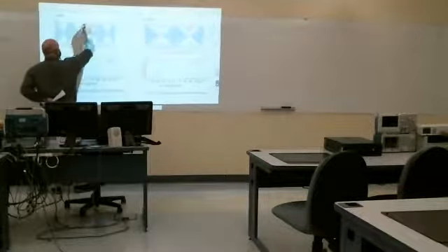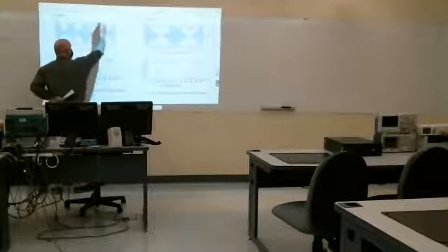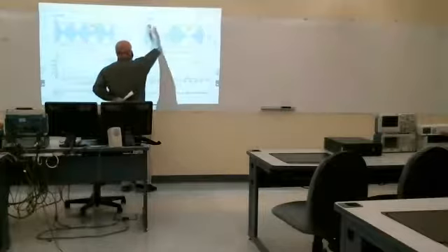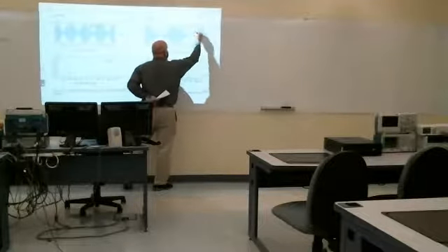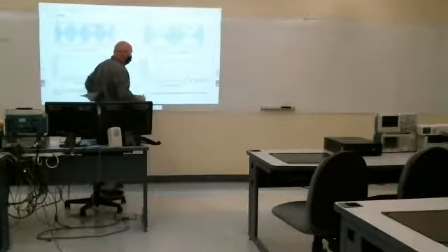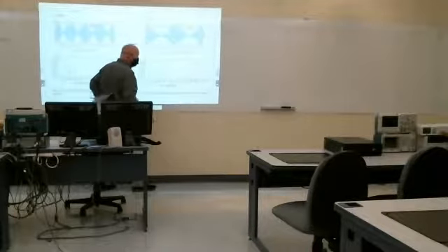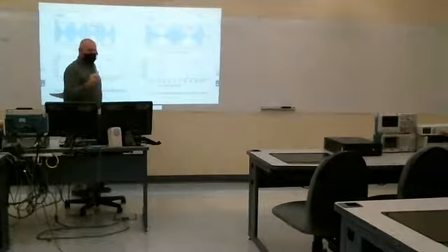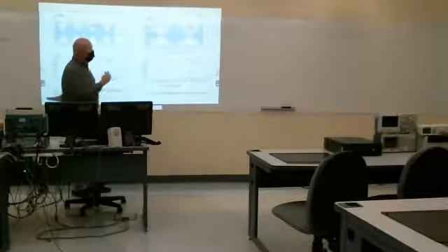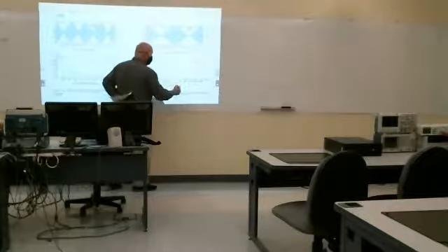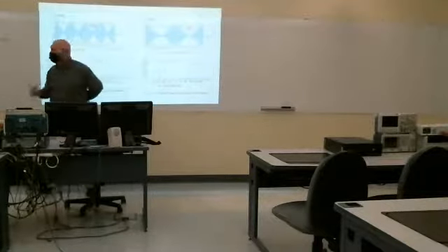Here, our cosine wave is actually this. Right? Now we've shifted that up, so here's that same waveform in AM. In AM, in addition to those 2 impulses due to the 1 Hertz message, we also have an impulse at 50 Hertz due to this term.